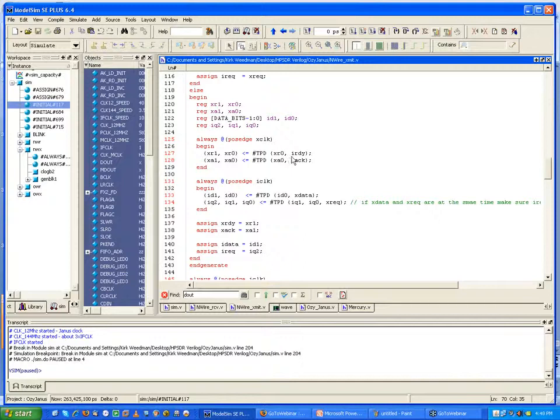So this is just a double buffer. Remember the double buffering? That's all this is doing. So see, I ready gets clocked into XR0, XR0 gets clocked into the XR1 flip-flop. Does that make sense, or do you want me to draw it out?